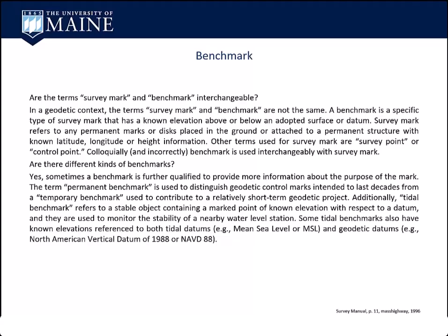You're going to establish a lot of control on buildings, and they're just single elevation only. They'll be tied into the building, but when you're just running through and hitting in a deformation study, you're just hitting these previously established benchmarks with elevations to see if they're settling or rising.